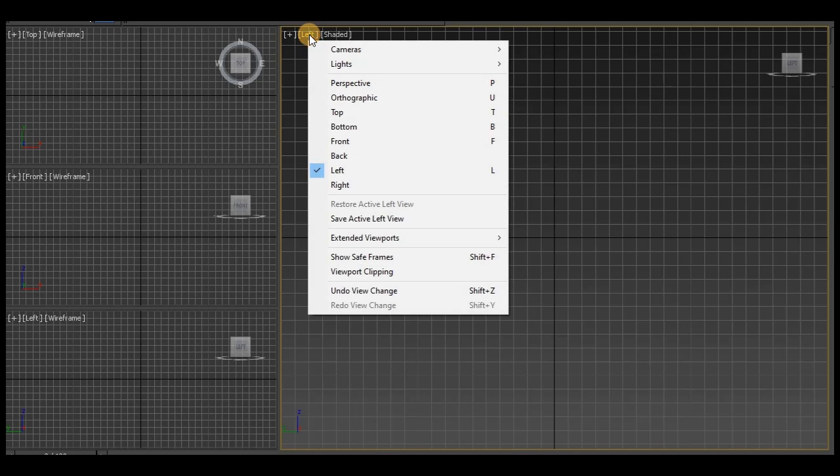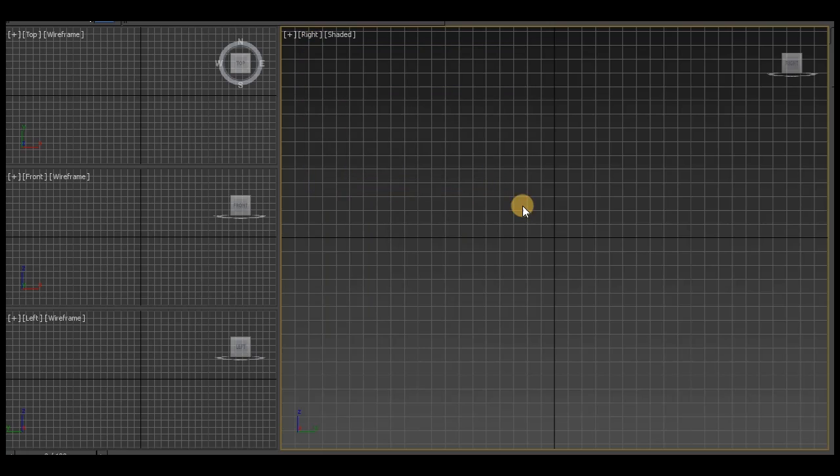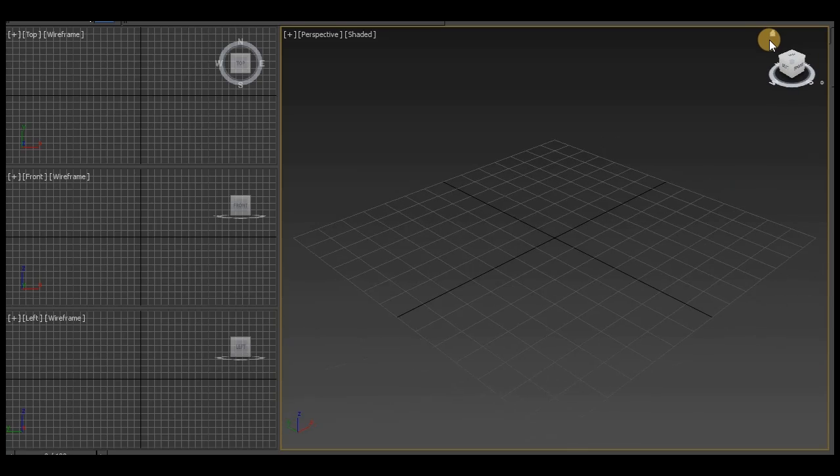The different shading types are realistic, shaded, consistent colors, wireframe, edged faces, bounding box, hidden line, and so on. However, some of the shading types are available in the cascading menu of the Stylized option. Refer to figure. Those shading types are graphite, color pencil, ink, and so on. You can choose any of the options to change the shading.